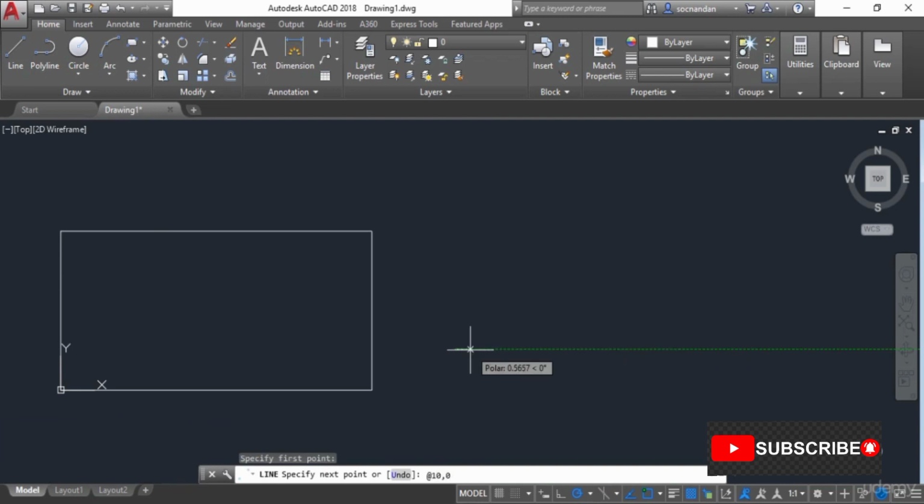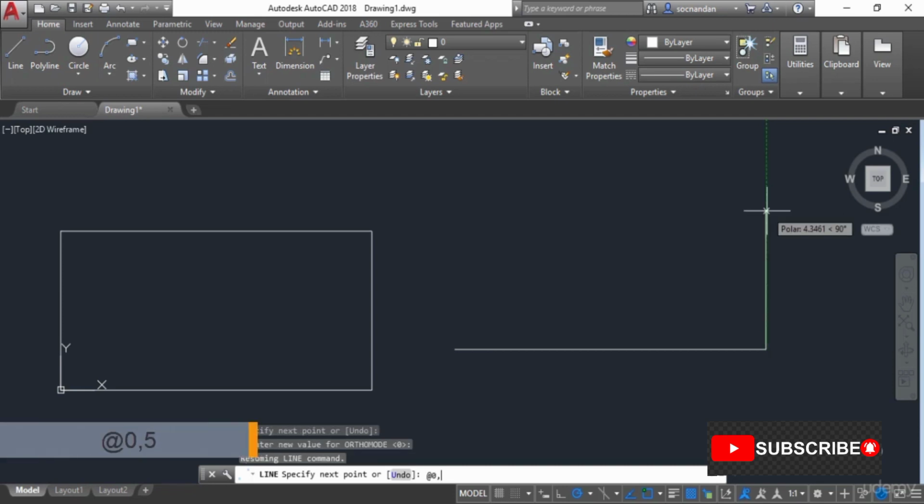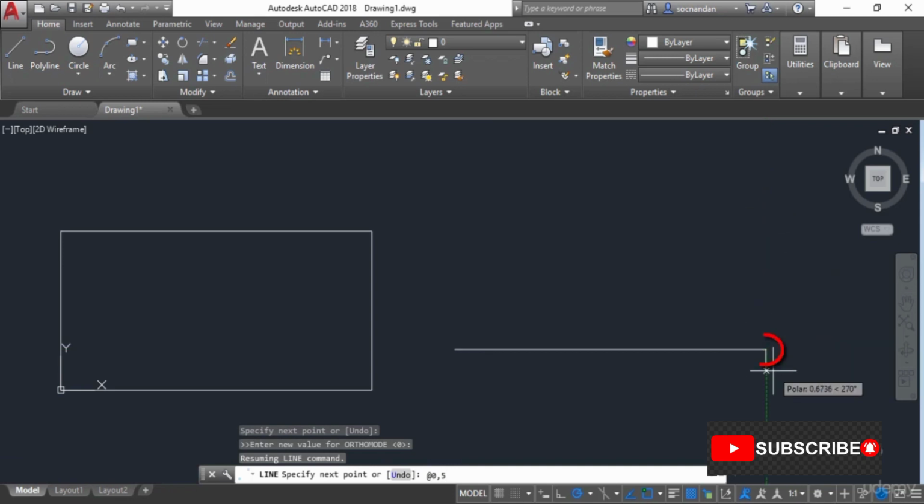Now AutoCAD will assume this point, the starting point, as the origin, and now it will make a line of length 10 units. Now if you want to take this cursor upwards, and make a line in the upward direction, you can again type @0, 5, because in this case the origin will shift to this point. So whenever you add an @ sign, the origin will shift to the previous point where you have clicked. So if this is the origin and we want to make a line of length 5 units in the upward direction, the coordinate of that point will be 0, 5.